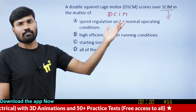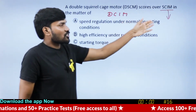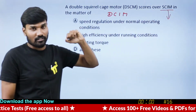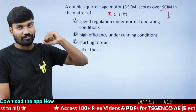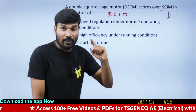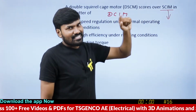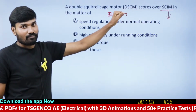Why not use a slip ring induction motor? If you use a slip ring induction motor, yes, torque is controlled. Starting torque can be controlled, that's for sure. But the maintenance problems are high for a slip ring induction motor. The running performance is better for this. Starting performance is poor, but running performance is better for this.